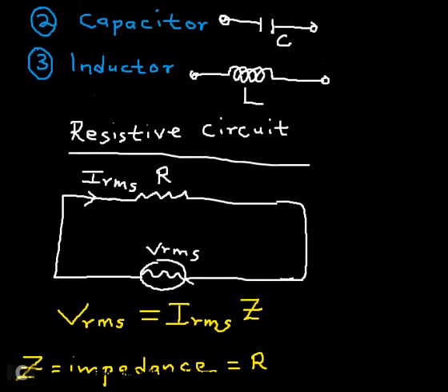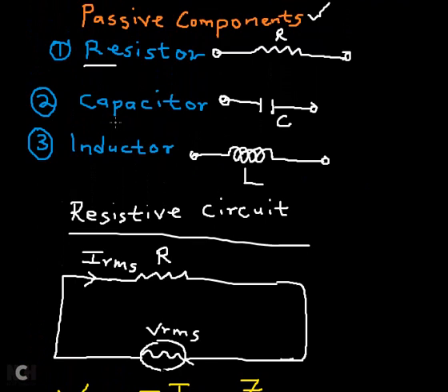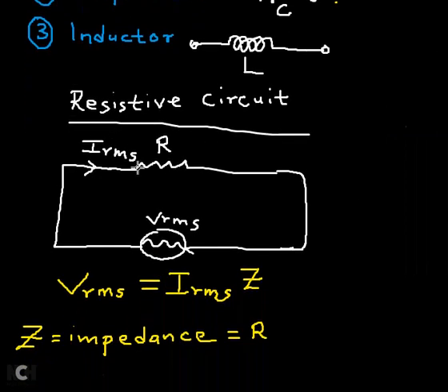Now reactance is simply the opposition or the delay. Any component that provides reactance to an alternating current or voltage causes it to either delay or have a phase angle. What I mean by delay is, if a current was supposed to start from the origin, then it delays. That can only be caused by a capacitor or inductor. So they are the components that can provide reactance. But a resistor doesn't provide reactance.